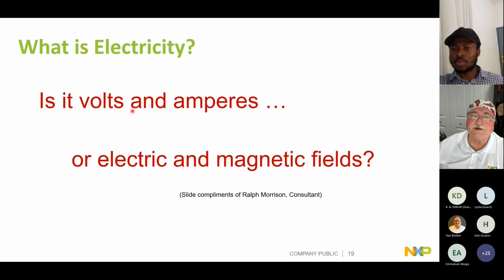And in my naivety, I found that if I needed to look at something that was switching very fast, I needed a FET probe. And I was like, FET probe, FETs are faster, right? That's not why they were allowing you to see faster circuit signals. It's because on a FET probe, you have a really tiny ground lead, and it has to be very close to the signal point. So it takes a whole lot less time and less field to fill that space than it does with the 3-inch long ground lead. So you can see changes in field density faster because it takes less time for it to happen. Interesting. It's time and space.